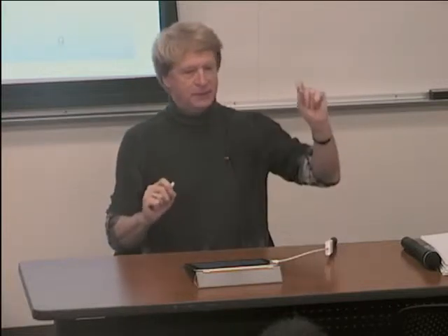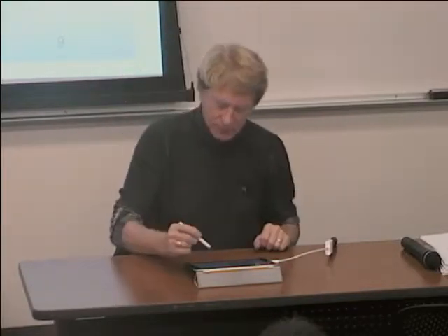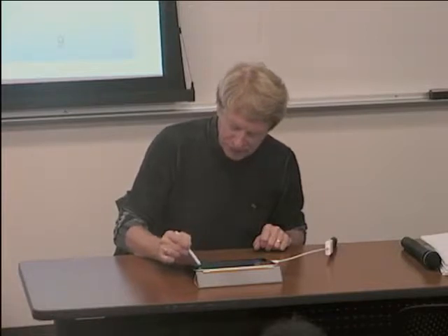And the same thing with the NMOS. I have a fast model, a slow model, and a nominal model. Now, what I can do is simulate my part not only with the nominal transistor models, but also with all the 4 corners. Because now what you have is like, you look at PMOS, NMOS space. This is NMOS, this is PMOS. This would be my normal operational point.